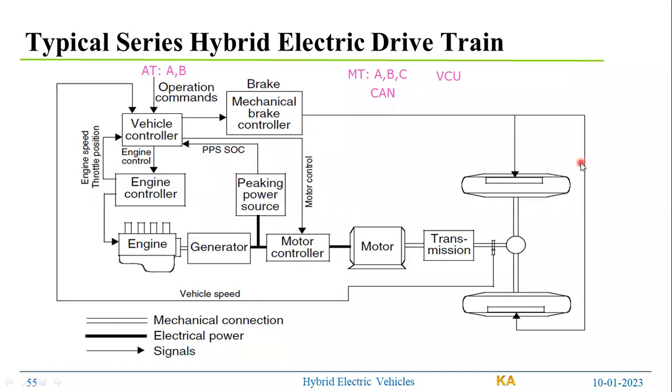And when it actuates the brake actuator, there is one more action the motor should do. When the brake is applied, the motor should go into generator mode, the motor controller works as a rectifier, and then charges the battery. So that is the third operation it will perform. So overall, whatever commands we give, that should work.